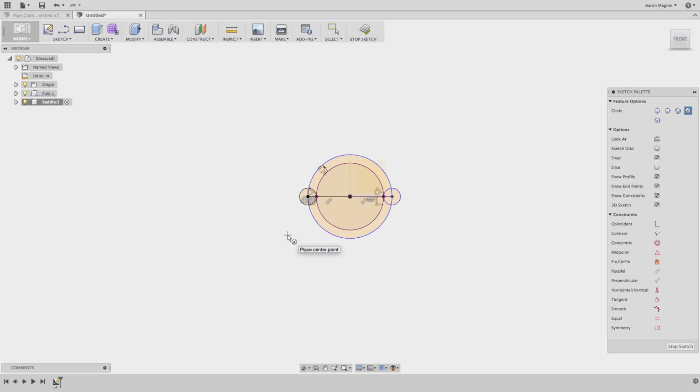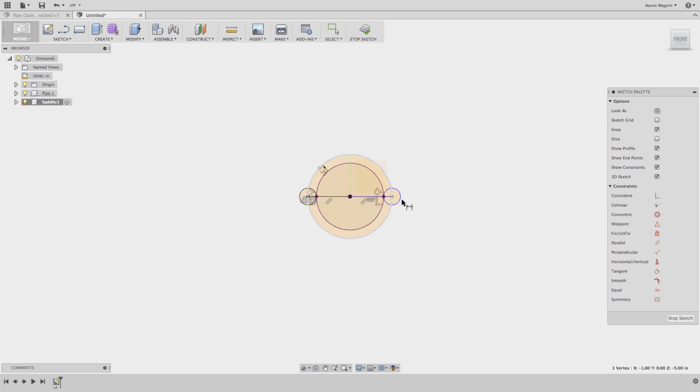And I can continue to add other dimensions and other details to this. I can use my right click drop down and access my sketch dimensions. I can say, I want this to be a certain size. I can make things equal to one another by selecting them and using these sketch constraints. You'll see that it won't even allow me to do that because they are being forced to a certain size by the relationships that I added there. So I think we're good with this sketch.